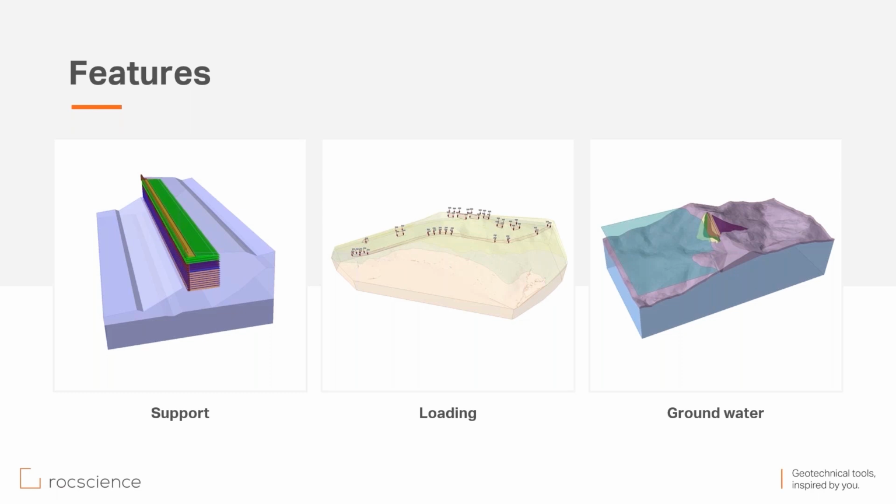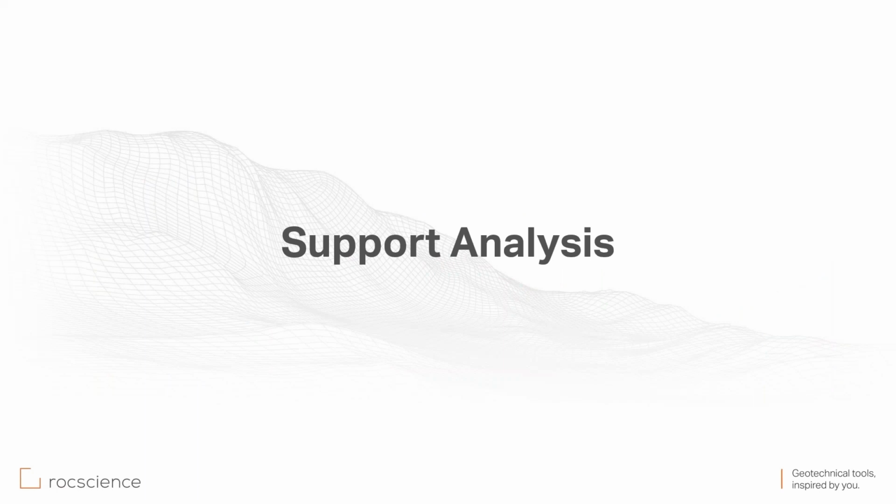Supports, loading, and groundwater are the features that we have in the Slide 3 software that I'm going to talk about one by one. And I'm going to explain how to use these features with several examples today. Let's start with the support analysis.